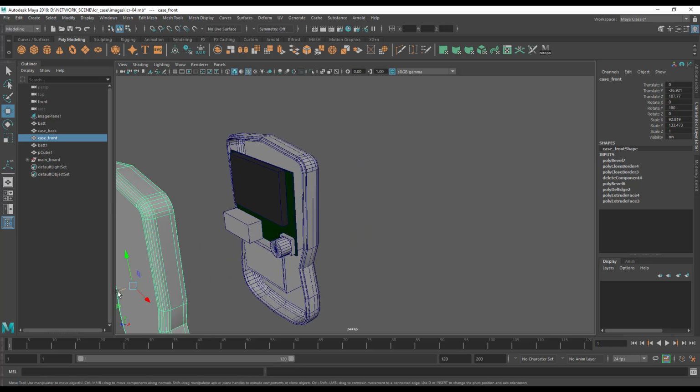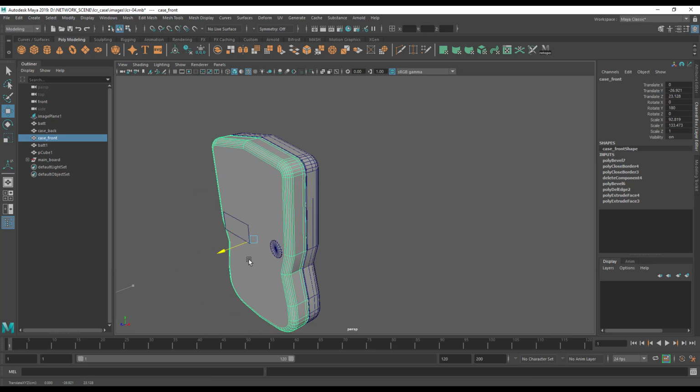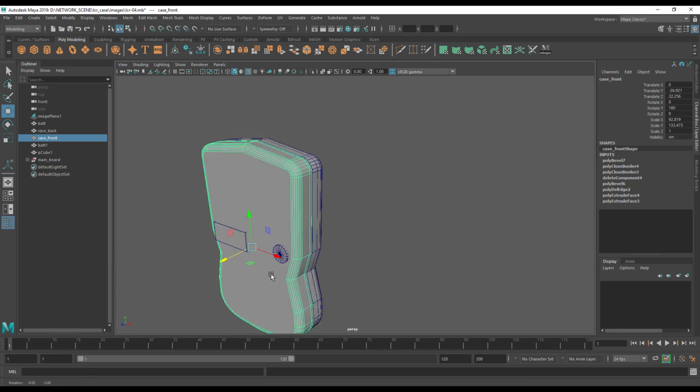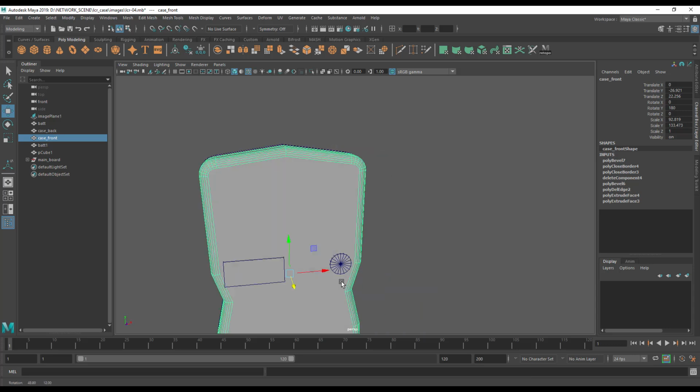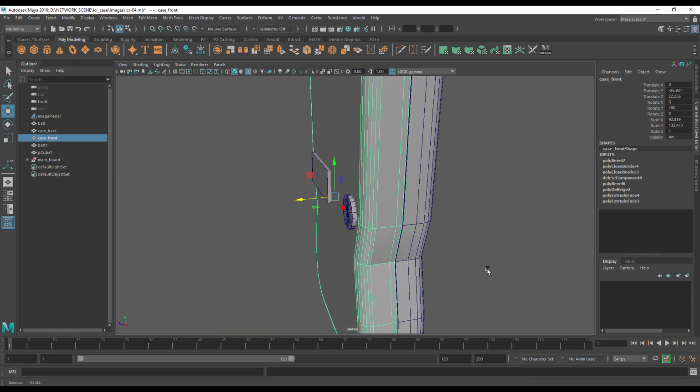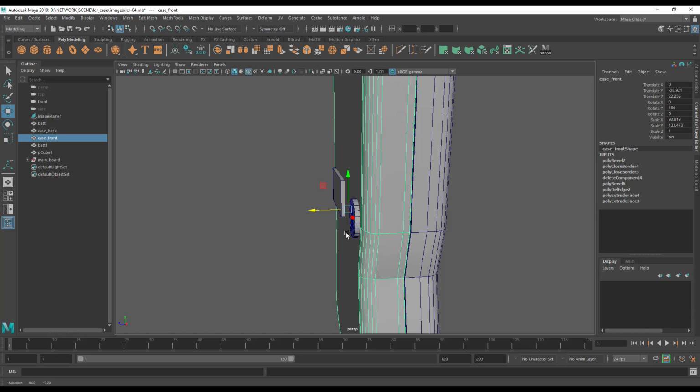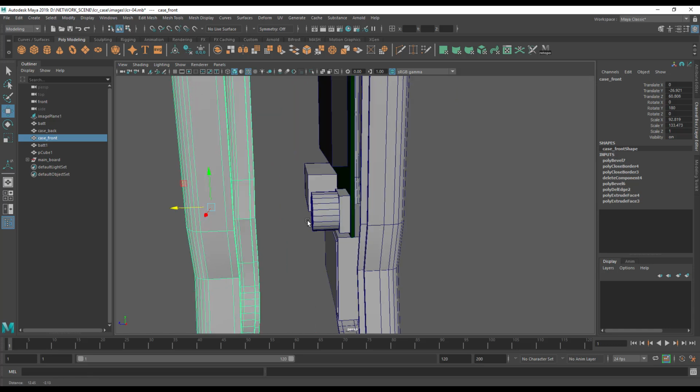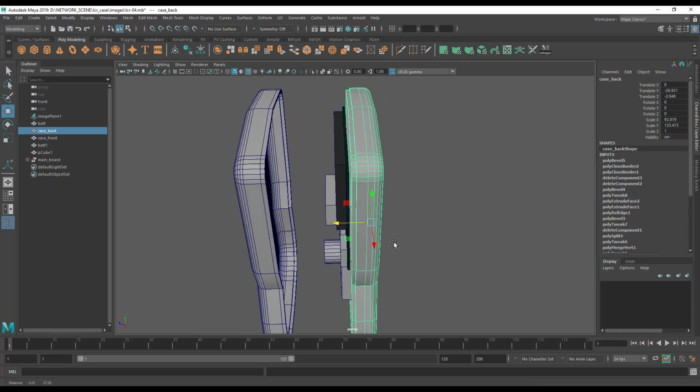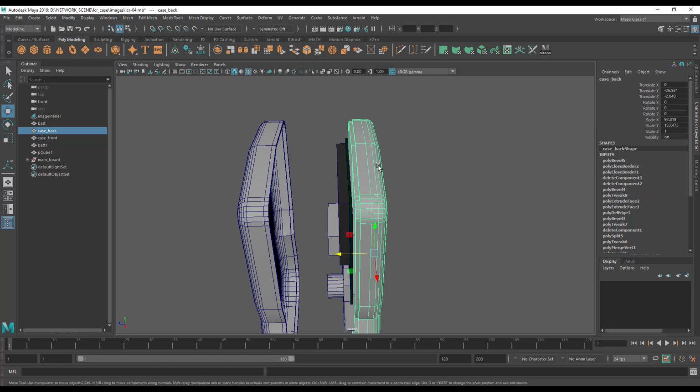And let's move this to a point where that becomes a reality. So as you can see, already when we move in, the ZIF socket is proud and the button here is proud, but that's not quite as far as we want to go. So a couple of ways we can do this. We can decide if we want the case to be a clamshell with two halves the same, or if we want one of these to be recessed.